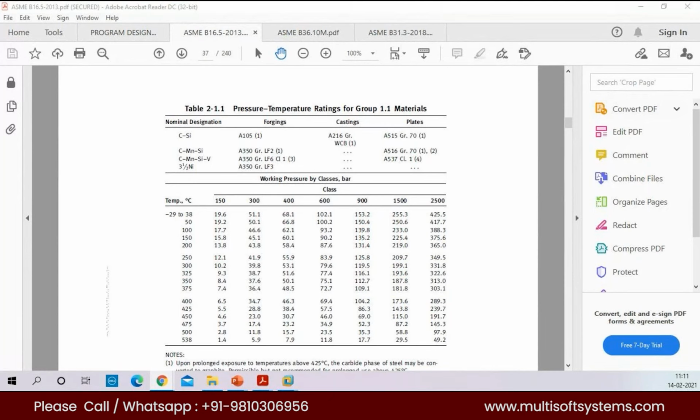Yeah, that's a worst condition, right? We can't use the worst condition in our project because we have to take fatigue analysis and everything into account. We have to take care of the lifelong, because when the heaters are running, the flexibility and the pipe stiffness will be reducing. That will not be standardized. So we can't specify that we can use the material up to 600. Like that we can't predict. There is a maximum up to 600 that we can use, but for the lifelong we have to consider, we can't use the material.